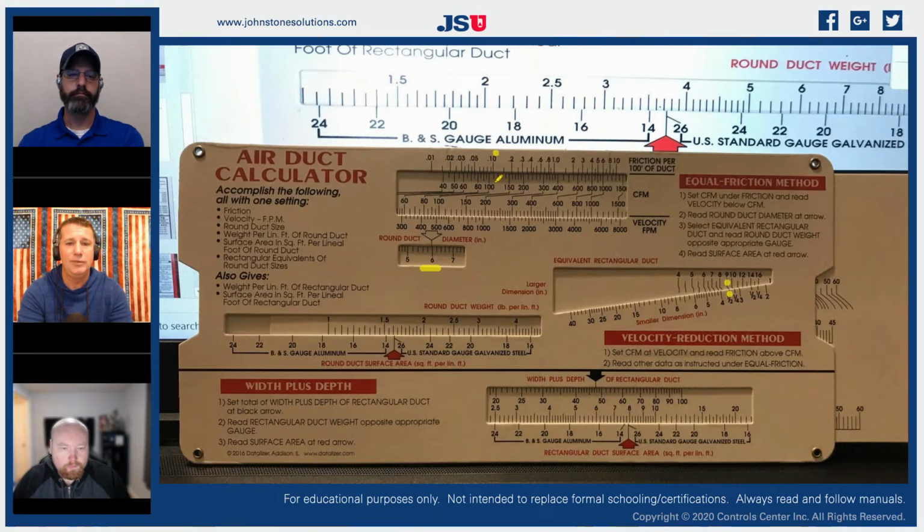And that would be good for about 110 CFM at 0.1 inches. But if we also look at that exact same chart and go, okay, well, what if I have higher static on my system? How much airflow can I get out of that 6-inch round? So Jesse and I have been on jobs where we've encountered over 1 inch of static on ductwork, right? Unfortunately, it happens in our industry.